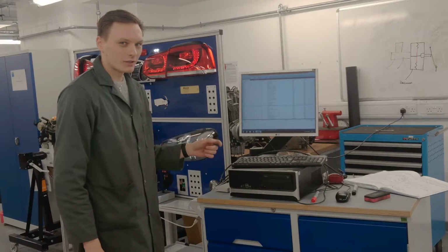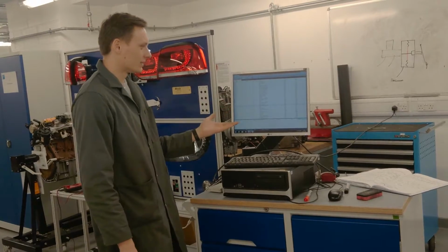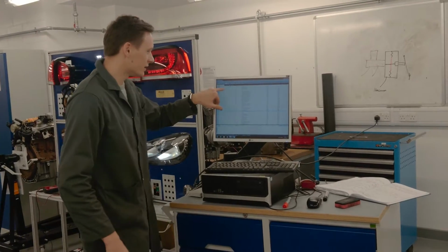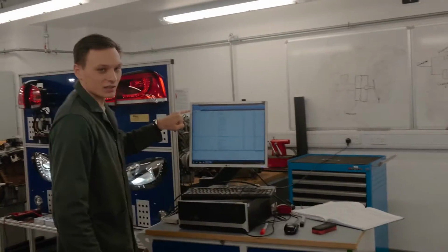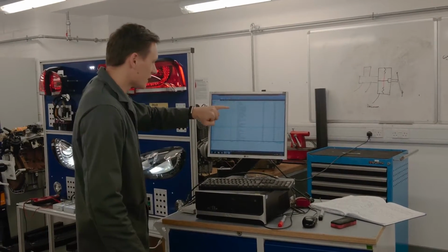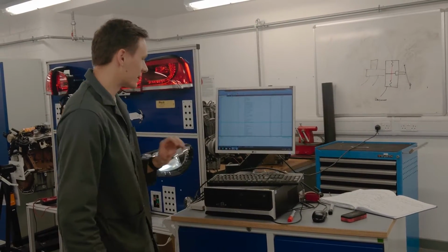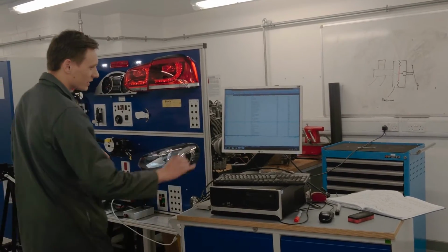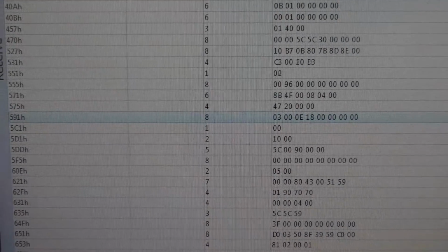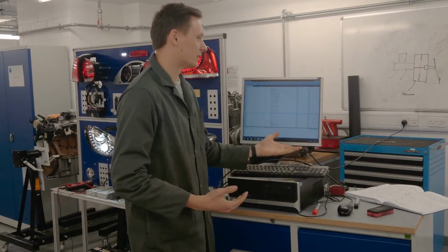Over here we've got PCAN-View software, which decrypts the data from the CAN bus system and puts it in a readable way for the human being to read. Over here we've got CAN ID, which is an identifier, the type of it, the length of the code, also known as control, the data, which in this case we just tested the brake light system. So if I switch the brake light, the code changes over here, and the cycle time, which is the cycles per minute, like counts per minute.